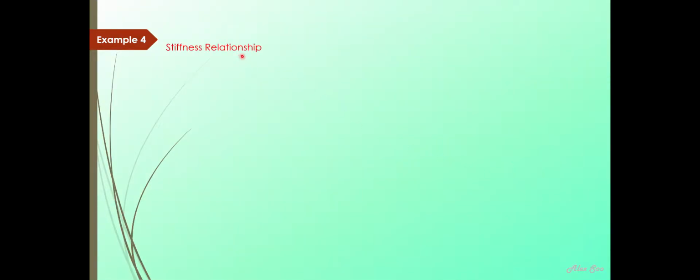The next part is based on the stiffness relationship. You have this equation based on stiffness or rigidity, where instead of shear stress over radius, now you have the modulus of rigidity times the angle of twist over the length of the shaft. Manipulating this, the polar moment of inertia equals TL over G theta. Putting in all the values of T, L, G, and theta, and working it out, you get 2.156 times 10 to the power of negative 6.